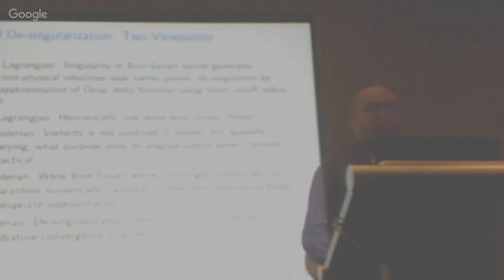This kernel here is the singular Biot-Savart kernel. It's notable that it's singular because, imagine you had a target point at which you'd like to evaluate your velocity that's coincident with a source point. This clearly blows up. Now, we know in reality that you don't have infinite velocities, so that's clearly non-physical, but also from a numerical standpoint, the fact that it's singular presents numerical challenges. So there are a couple of ways to try to work around this.